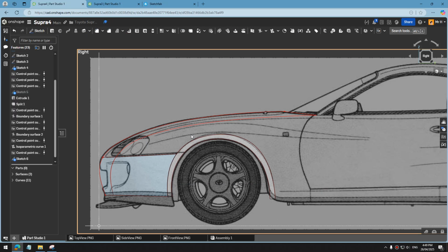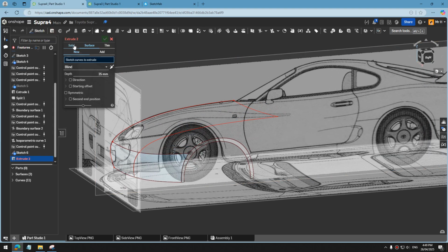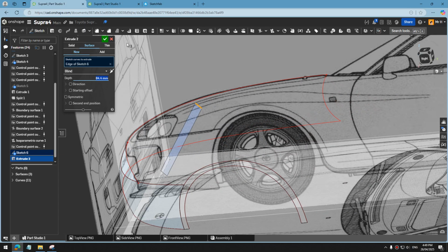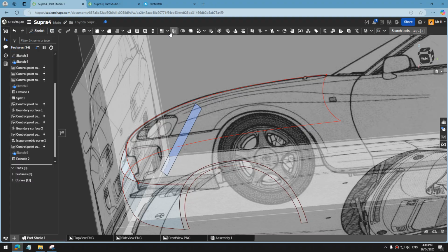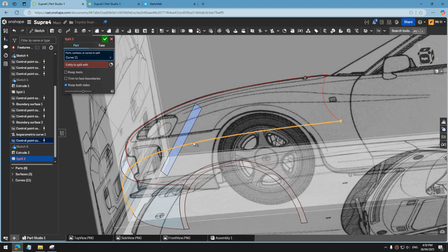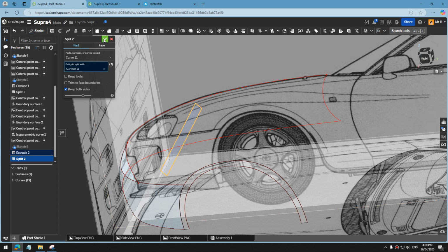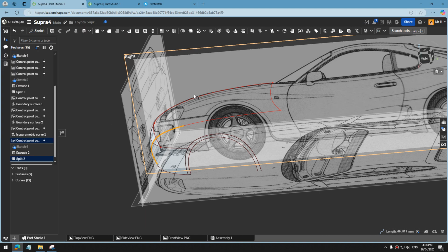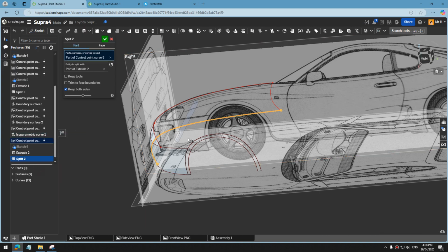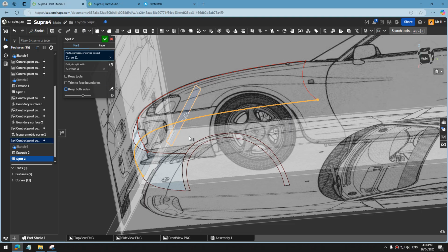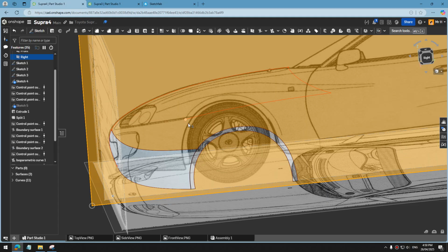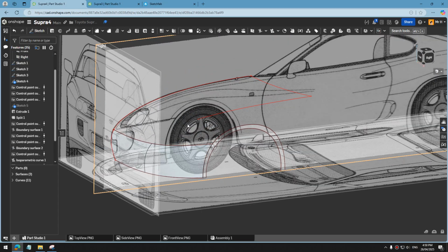Alright, we draw a line there, accept, and we go extrude, click on that little line, then we drag this surface across the line, and you're gonna go to split. So click that line, we click this entity to split, click on the surface, and click OK, and then it splits it right there. Or actually, maybe if you turn this off, it doesn't keep both. So we just trim it so it makes it shorter.